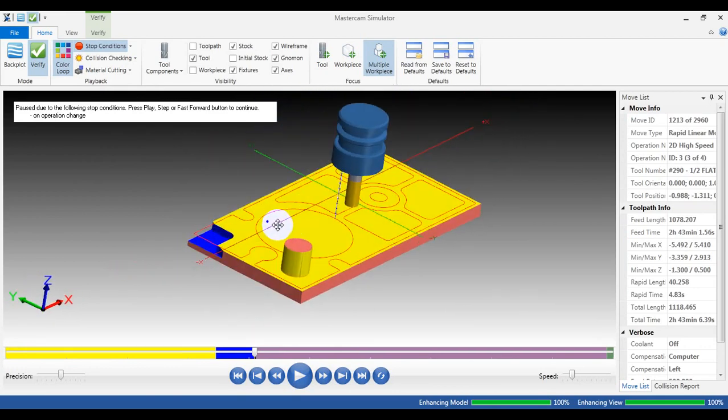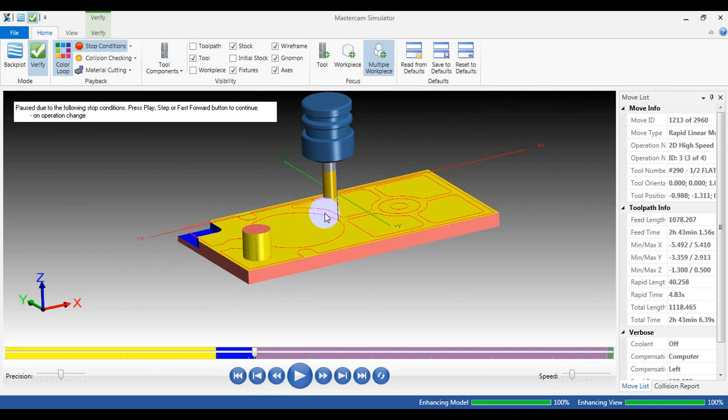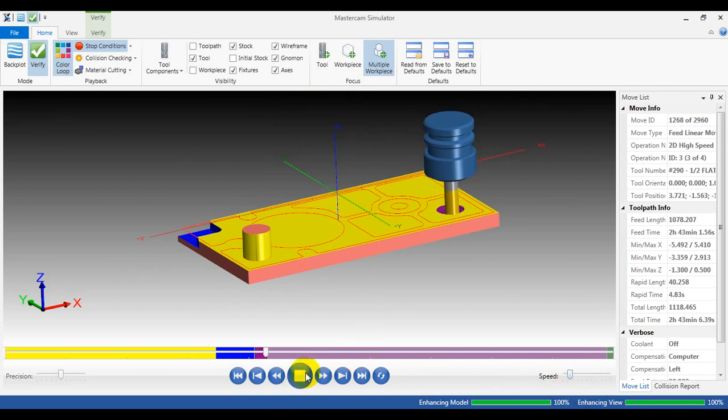And next, in the second video, I talked about the Mastercam dynamic mill with the stay inside option for a closed pocket. You can see we have the tool engaging from inside of the pocket with the lead-in motion.